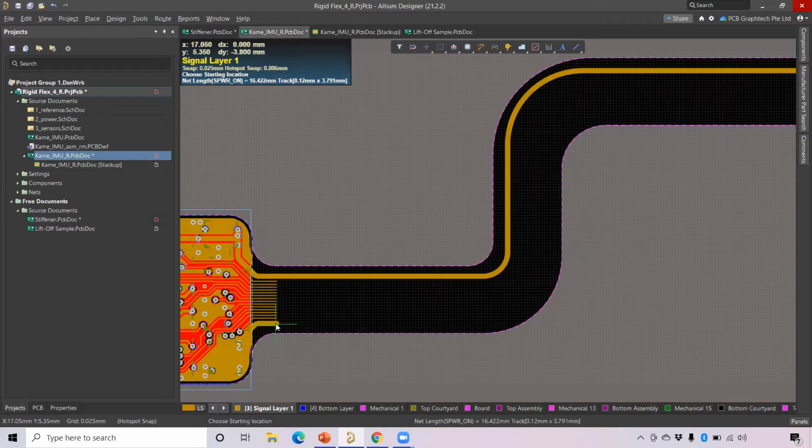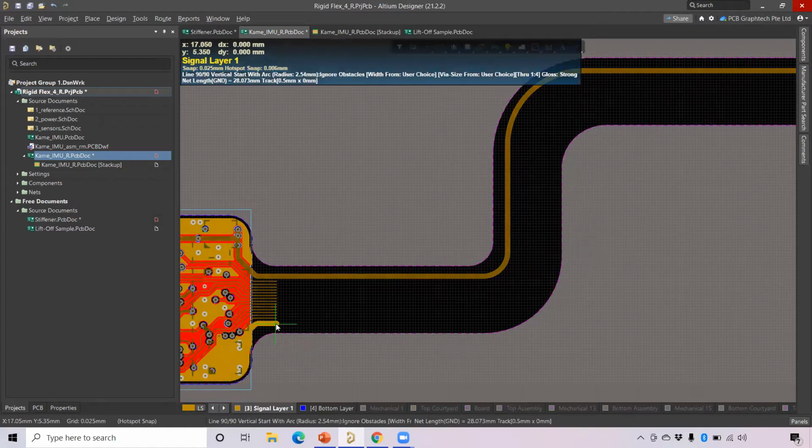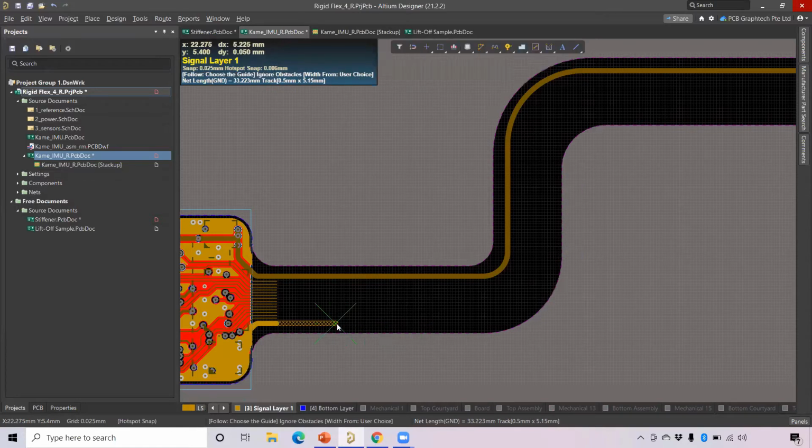Then if I want to do the same thing for the last line, instead of following the first routing, you can also follow the board outline. I want to follow the board outline routing. You can press Shift F and then follow. You see it is following, but when it is following, it follows with respect to the design rules. Based on the design rules clearance, it will follow for me to do the routing here.